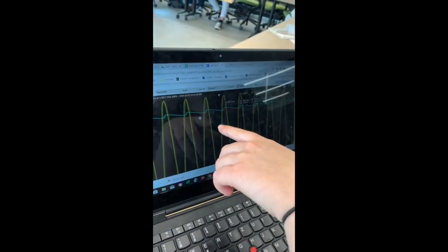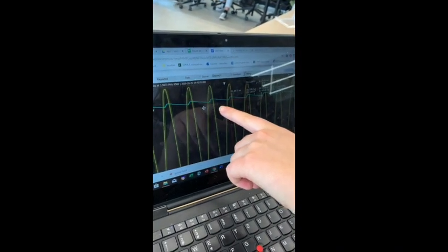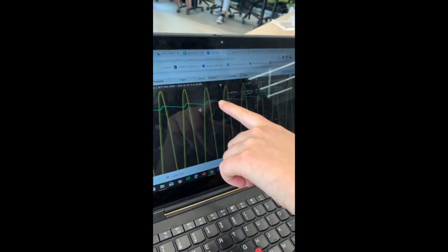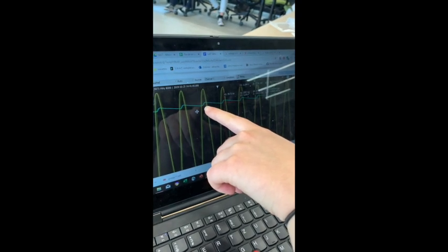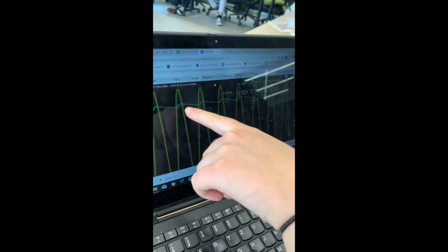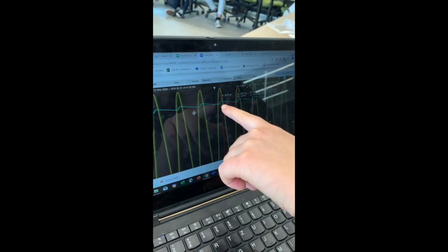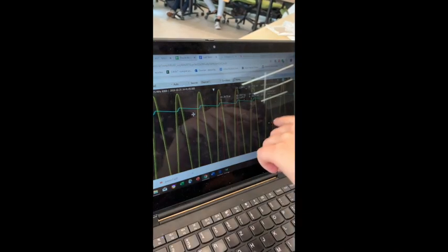So this is the waveform for when we have the capacitor in the circuit, and we can see that the voltage across the resistor, which is the blue one, takes some time to increase because the charge takes time to go up across the capacitor, and then it takes a long time to decrease also, as they need some time to go the other way through the capacitor too.